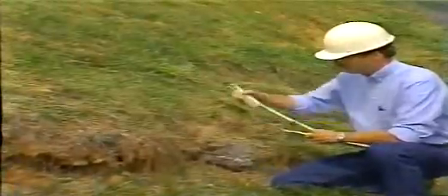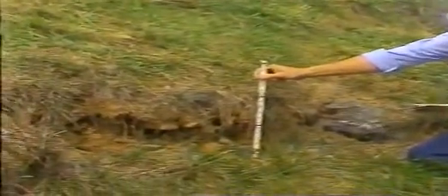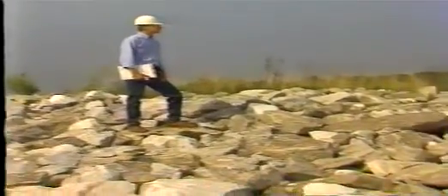Obstructions such as bushes or trees, material from slides or rock falls, and other debris can block the flow paths on spillways and outlet works. On the side slopes of earth or rock-lined channels, look for signs of instability or slides that are blocking or could block the channel. Check earth-lined channels for erosion damage or bare spots that could lead to erosion. Also check for undercutting of the slopes and possible slides. Erosion can also occur to riprap-lined channels if deterioration or displacement occurs to the riprap due to wave action.